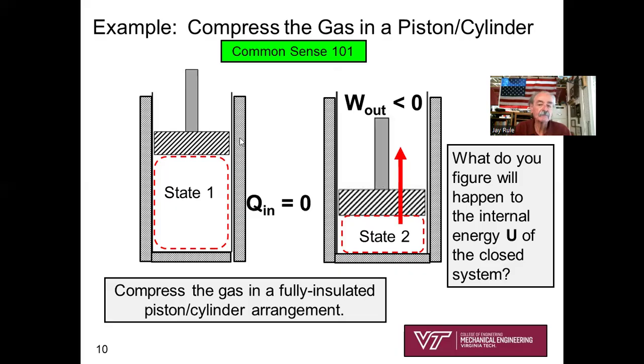And now some very smart students would say, now, wait a minute, you know that there is some substance associated with the styrofoam, so there will be some thermal communication between the cylinder wall and the surroundings. Now, I do agree to some extent that's true, but just imagine in your mind that we've got so much styrofoam insulation there that we have prevented heat transfer from the cylinder wall to the surroundings. So just kind of go with me on that. And in my sketch, I'm showing Q in equals 0.